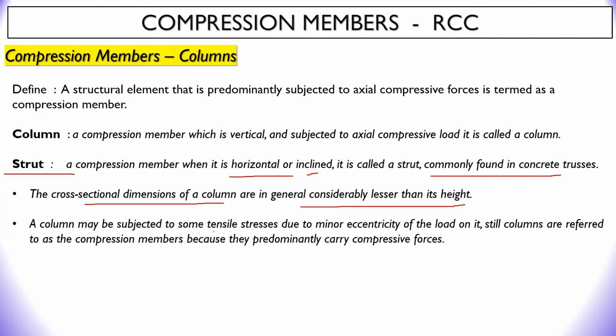A column may be subjected to tensile stresses due to minor eccentricity of the load, because we cannot assure in actual practice that if you are designing a compression member for axial loads, in practice you will find that there is the possibility of eccentricity of the load. So that means the load may have some minor eccentricity, and a column subjected to a load having minor eccentricity will be subjected to some bending moment, and due to that bending moment, ultimately the column will be subjected to tensile stresses.